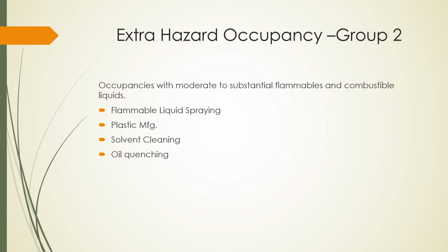For those people who are just on the cusp of sprinkler knowledge, the architects, real estate people, that sort of thing: once you're outside 5 feet of plastic storage, or I'm using 8 feet, although 12 feet is kind of the standard number, you really need to be speaking to a sprinkler professional to get further information as to whether or not the sprinkler system will be adequate.